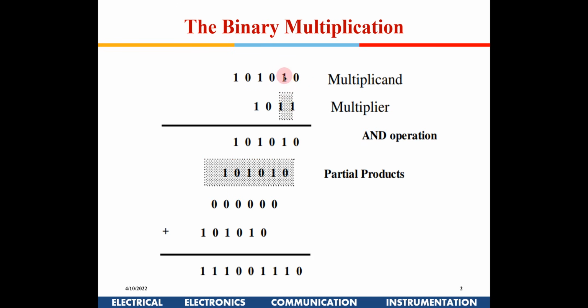Right. So how do we do a normal binary multiplication? Suppose you have 101010 to be multiplied with 1011. Normally, if you do a hand calculation, if there is a 1, this is repeated as it is at the bottom. Then we shift the next one towards the left, or you could say this is being shifted towards the right. Subsequently you take the next significant bit from the multiplier, and if it is 1, you just replicate what is written here.